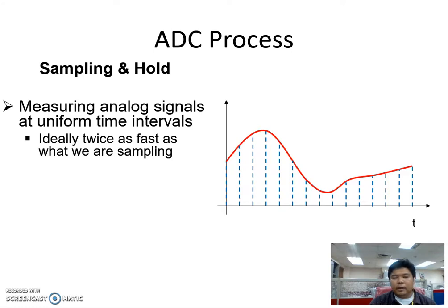Let's say we are sampling the signal every 1 millisecond. Every 1 millisecond we take the reading of where the signal lands on the y scale. We plot in two-coordinate form the height of the signal and the time of the signal. So what we're doing now is using the method called sampling and hold to make a coordinate form of the signal.